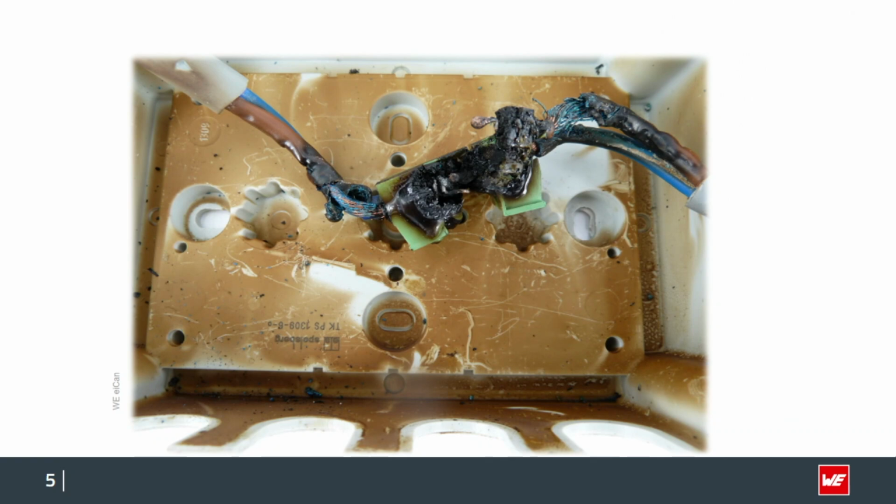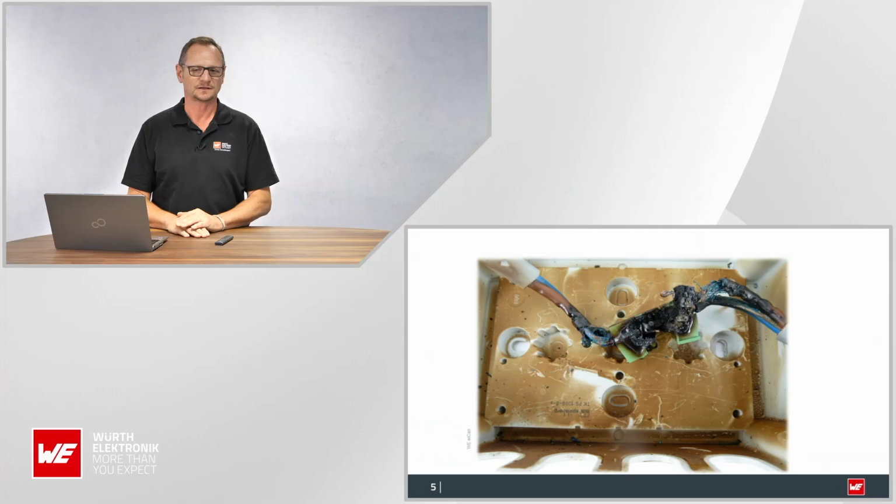There's a bad image. Everybody should get goose pimples if you see that kind of picture in your near environment. This is a true picture we received from a customer with one of our connectors, but not because our connector was not able to withstand the current. Of course, it was a failure in point of temperature. That means we had too much current on this connector, and therefore it got too hot.